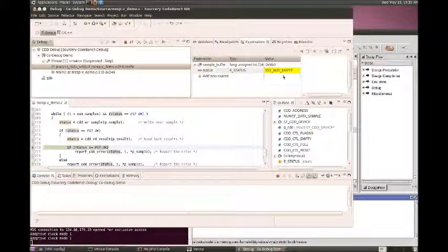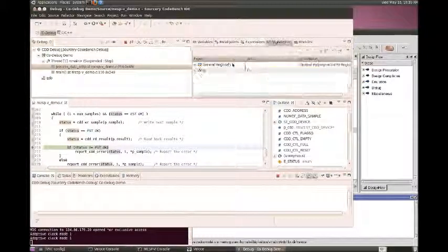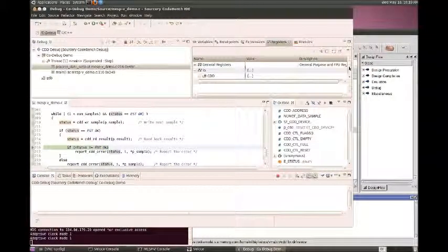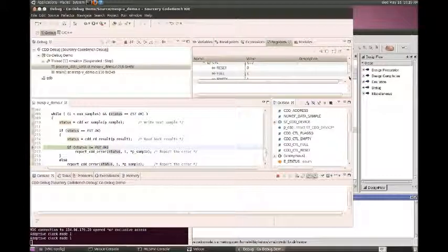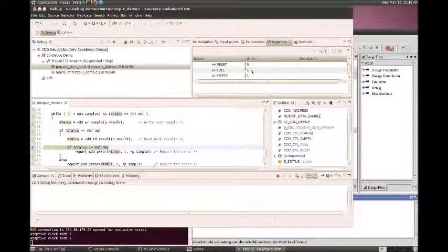When we try to read the results, we see the status shows that something has gone wrong. Let's look at the accelerator's registers to see what's going on. So the control register is empty, as it should be after reading the result register, but it also shows that it's full. How can it be both empty and full at the same time? Since the hardware accelerator control register is in an unreasonable state, I'm starting to suspect a hardware problem.